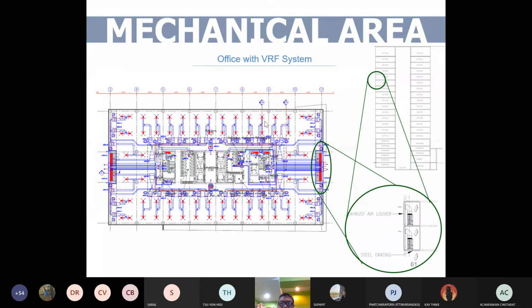In the other way, in the afternoon, they have no sun on the east side, but they have sun on the west side. So the load will be open here 100%. The electronic expansion valve on this side of the building will open 100%, but this side maybe only 50%. So the total load will be less than 70% or 80%. So the VRF will help you create load sharing and a diversity factor similar to chillers.